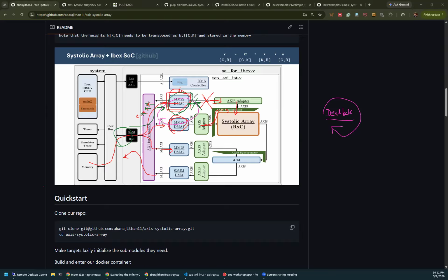So at the end, how I solved it is basically like this. I took this signal from here. On this side, we know whether this line is blocked or not from the ready signal that comes from here. You use that ready signal to mask the request bus here. The request bus is AR, address read. You take this AR as the access stream bus, and you mask it. Mask means you take this valid and ready signal and you AND it with the valid that goes here, and the ready that comes back from there.